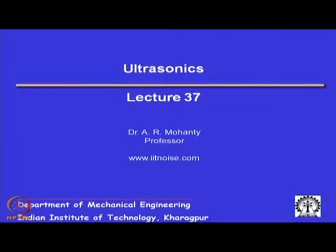This lecture is on ultrasonics, which is another technique of NDT, which is predominantly used in condition based maintenance as a non-destructive test technique to evaluate the effectiveness of, for example, welding, detection of cracks and so on. So, we will look into the principles behind ultrasonics in this class, a few applications and recent developments in ultrasonics, that is the phased array technology, which is used in getting an overall idea while doing an ultrasonic scanning on an equipment. Okay.